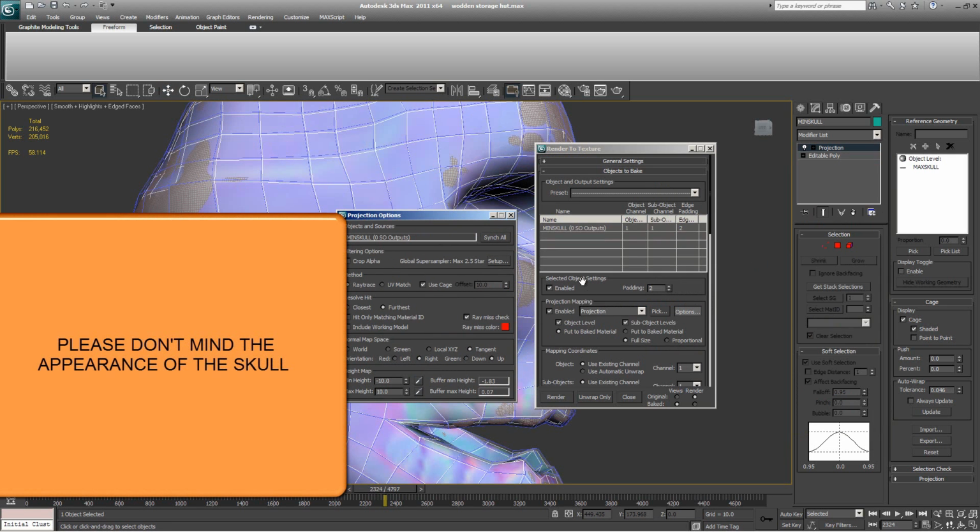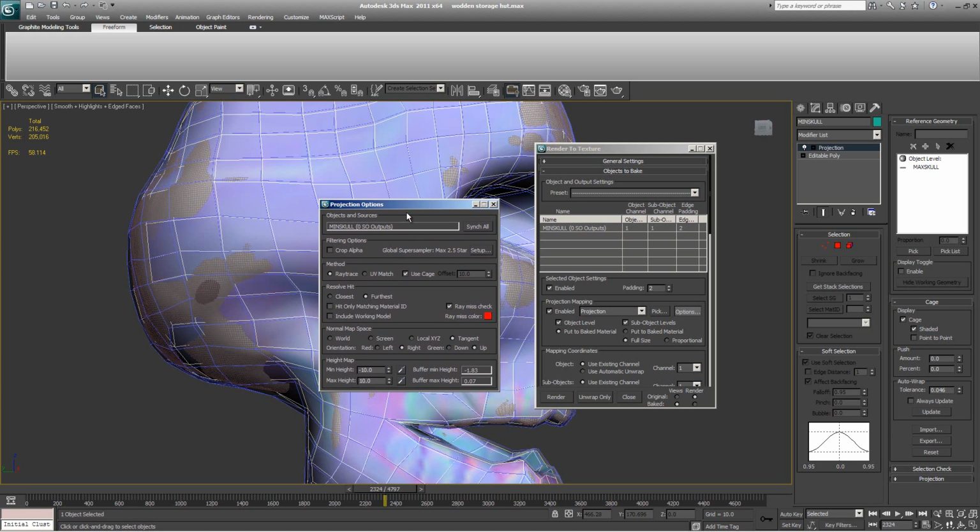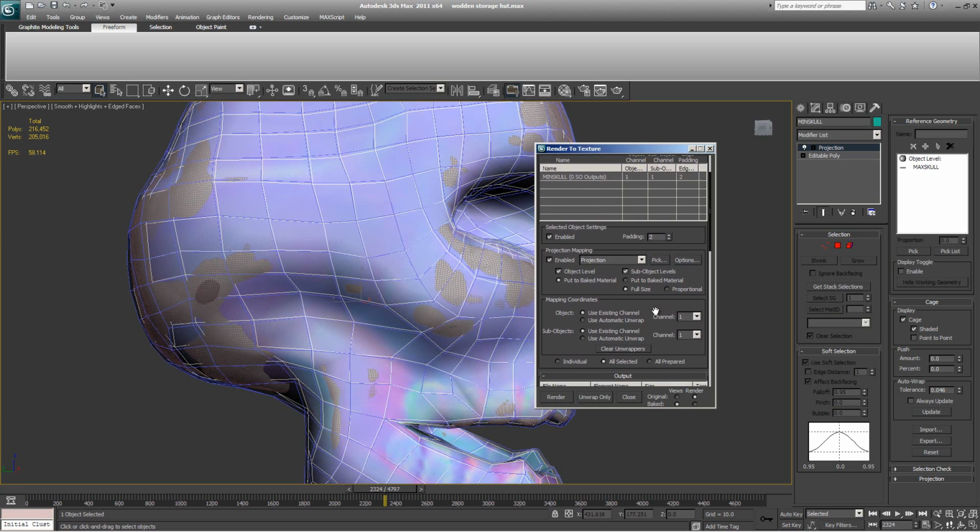Having done this, there is one more and very crucial part that you should pay very big attention to. When exporting to Unity the model and using the texture of normals, it requires you to change the green from down into up, and that the red orientation should be on the right. So red on the right, green up, and everything else should be okay. So use the cage should be on, and we're done here.